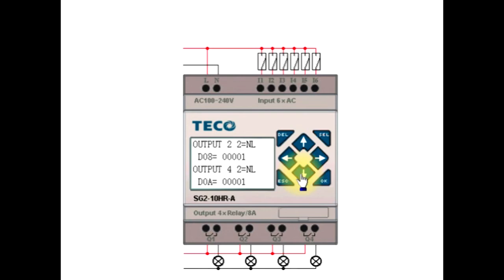This next screen is strictly set at the factory, where it allows us to reallocate output number 2 and number 4 for different outputs. For example, 2 is normally going to be material 2 load, but if you have a single material loader, we can assign that to no load alarm. It allows you to use many of the features that you might need on the larger PLC on the smaller PLC. Gives you more flexibility.